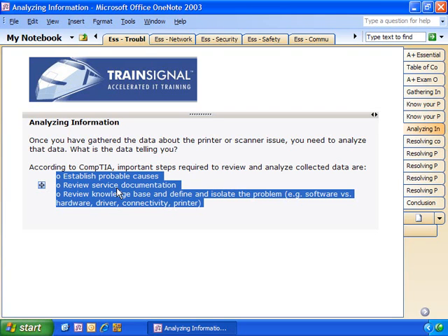Periodically, yeah, you change the oil, but at 50,000 miles, you have your major service done where the car is taken apart, the belts are analyzed, the air filters changed, all the parts are lubricated, and so on and so forth. They have this long list of things that has to be done at this major maintenance interval.